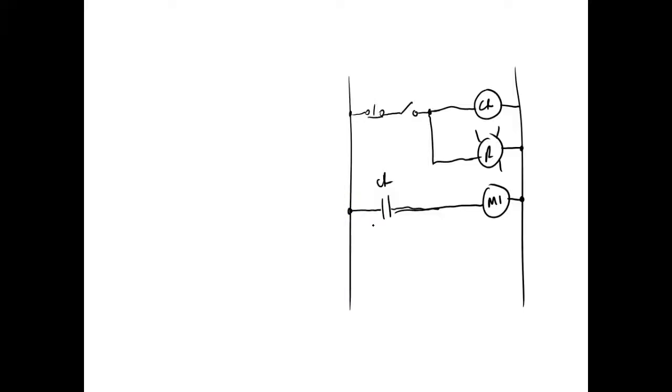No, we call this control relays. I'm just using CR as a generic term. You know, they're going to have a name. A control relay is a relay that never leaves the control circuit. So normally what we do is we have two circuits. We have what we call a control circuit.